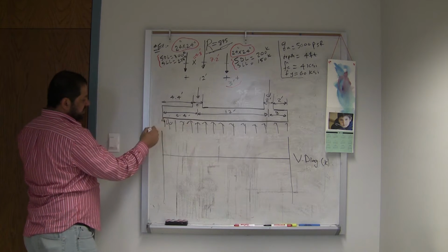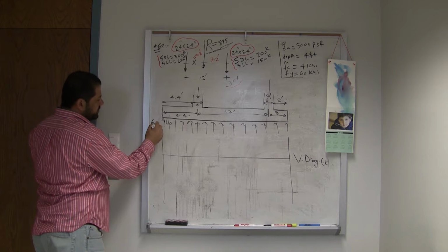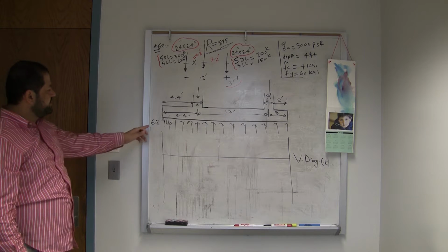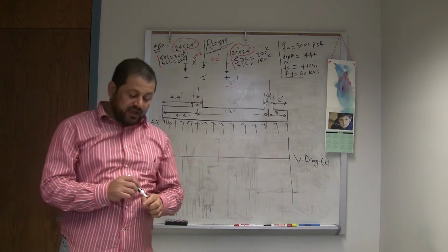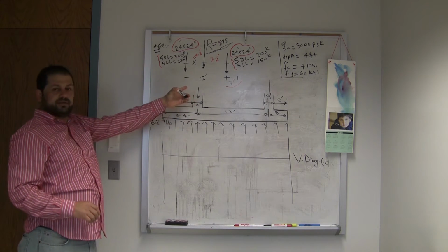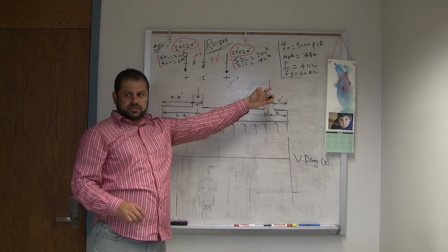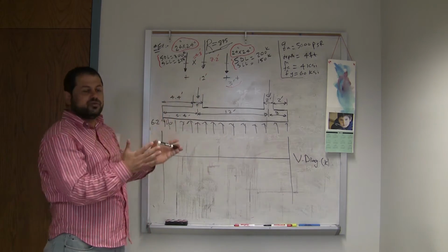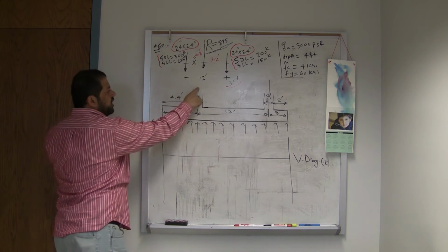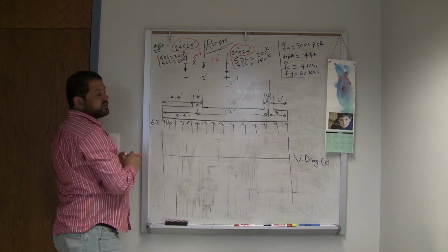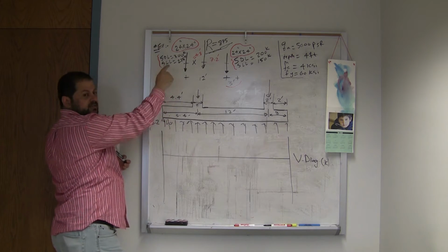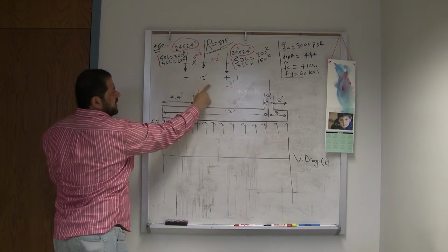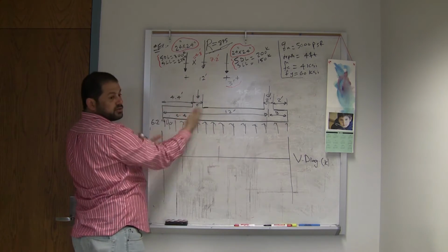Again, we said this bearing capacity is 6.2 kip per square foot. You have to be careful: the loads here must be the ultimate loads. Now R doesn't exist anymore. R is used to center the column. So we need to know the ultimate load in this column, which is 1.2 times 300 plus 1.6 times 225. We need to know how much ultimate load is in each column. You cannot just have R now and draw for R.